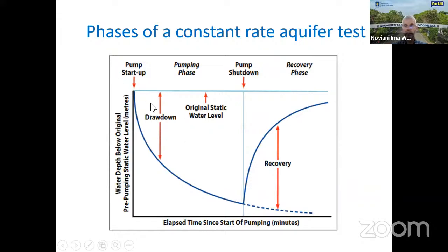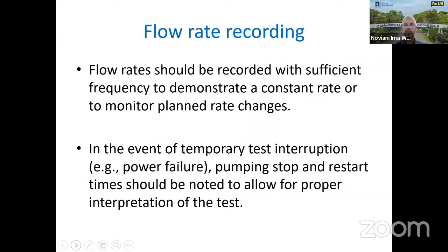So in our aquifer test, we're doing this part first, pumping, then eventually we're done, we turn off, but then we're not going home. We're also recording the recovery of our well as it happens when there's no pumping going on. All right. So you end up with a data set that has both drawdown and recovery. So the flow rate is something, like I said, you determine either variable or constant.